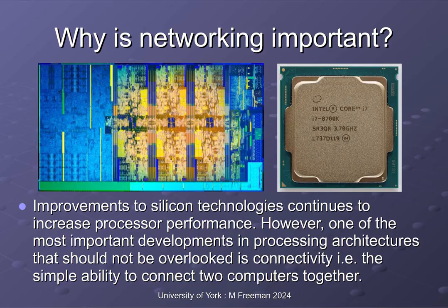So you've got a system bus. But you can't keep bolting on processor cores to a bus. The bus will get ever bigger and bigger. Effectively, the capacitance of that one will limit its clock speed. Basically, the loading you're placing on that one communication channel. So again, we hit bottlenecks in our silicon. And in this sense here, a communication link.